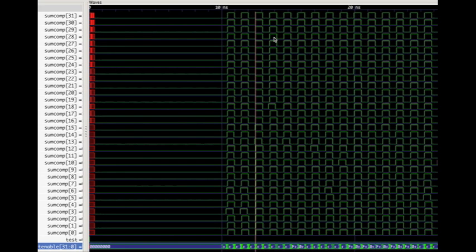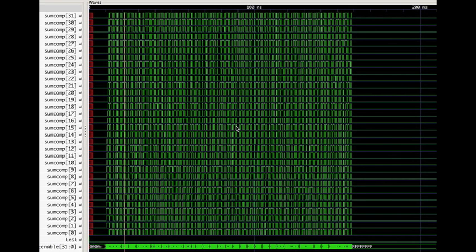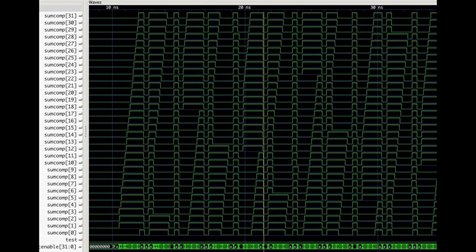This is the combinational shifter, and this is the pipeline shifter. And this is the one where we presented the 2D pipeline flow to the shifter. The 2D pipeline flow was presented by an incrementer that incremented 0. It didn't change the numbers, but it presented a 2D pipeline flow to the shifter. So we'll expand this a little bit so you can see the structure of the wavefront flows.